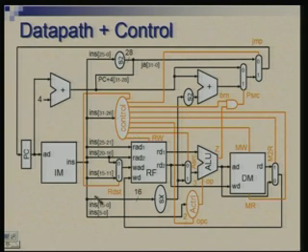You can take it that with the number of input lines, the size of circuit or the complexity grows generally exponentially, but with outputs it will generally grow linearly. So, we are more worried about keeping the number of inputs as low as possible. If there are large number of inputs, then we can look at parts of it separately and then combine the result. That is always a better strategy, and that is what we have followed.